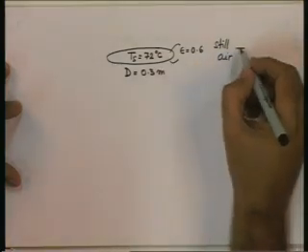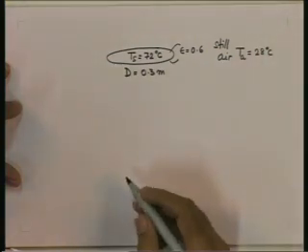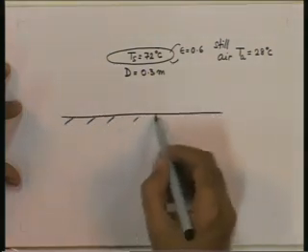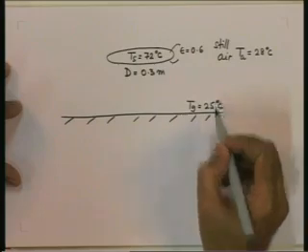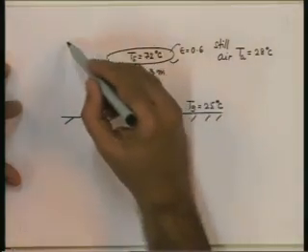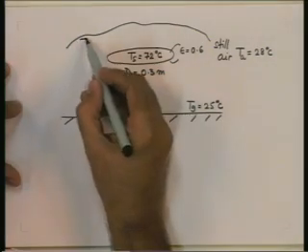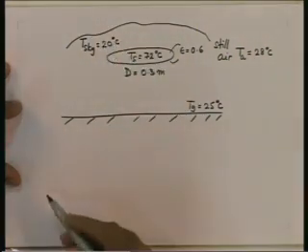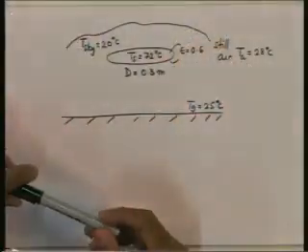The ambient air is at a temperature of 28 degrees C. Well, the plate is at some distance from the ground, and the ground temperature is 25 degrees C. And the top surface of the plate is exposed to the so-called sky, where you can say the temperature of the sky is 20 degrees C. Now the plate is warmer than the surrounding temperatures, and hence it will lose heat by natural convection and by radiation.